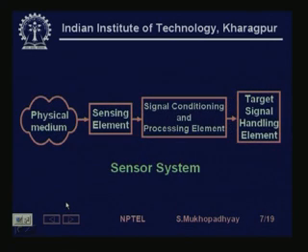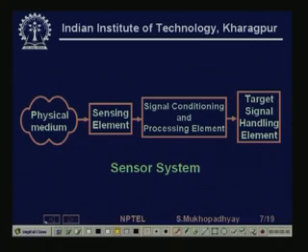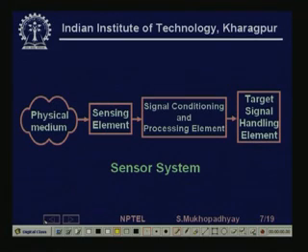So first let us look at a sensor. What is the job? The job is to produce information which accurately represents a physical variable. So obviously some variable conversion is required. This information is generally first obtained in electrical form, and after that it is converted into pure information form using digital electronics.